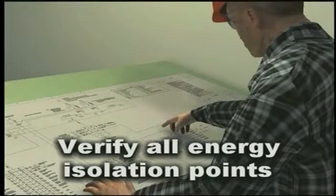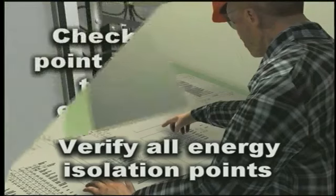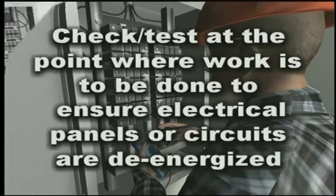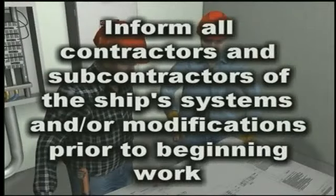Let's look at some of the contributing factors that led to this fatality. Employees should verify the location of all energy isolation points. Employees must check or test electrical panels or electrically powered equipment to ensure they are, in fact, de-energized before working inside them or within the vicinity of exposed electrical circuits. Inform all contractors and subcontractors of the ship's systems and/or modifications to the systems prior to beginning work.